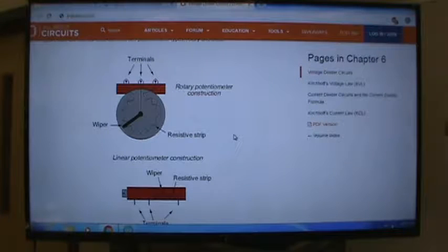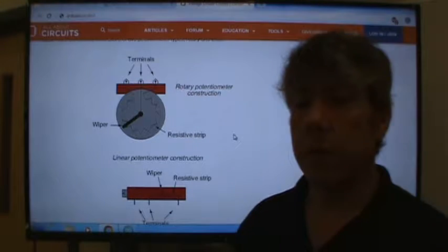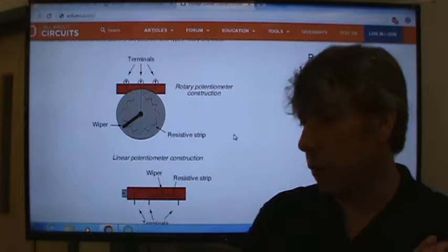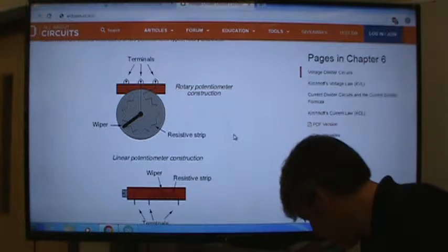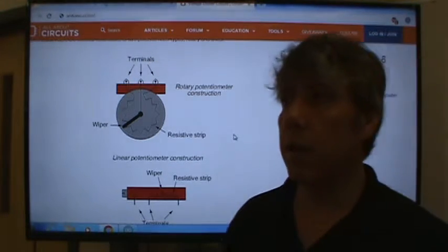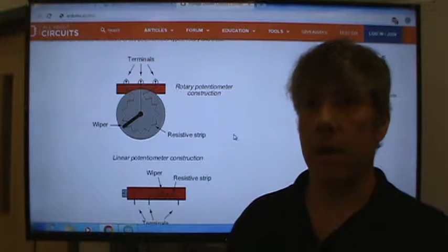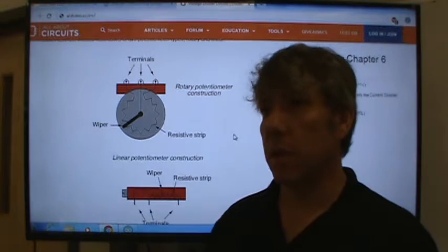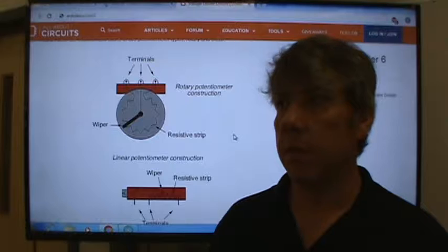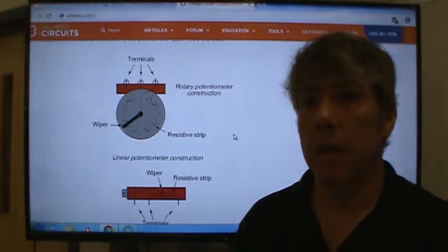Okay, we're going to talk about using analogRead on the Arduino. The way it works on the Arduino, there are 6 different pins, A0 through A5, that you can use for reading analog signals. Now, a digital signal is an on-off, a high-low, a 0 or 5 volts. An analog signal is something that varies.